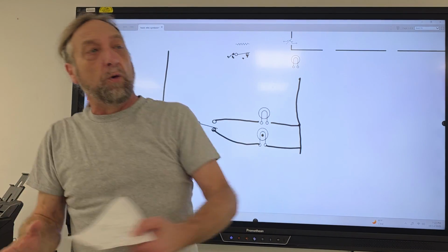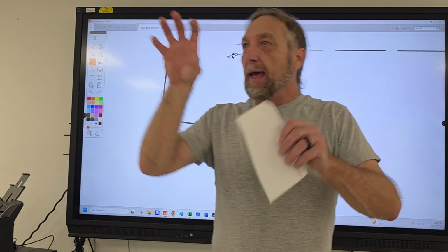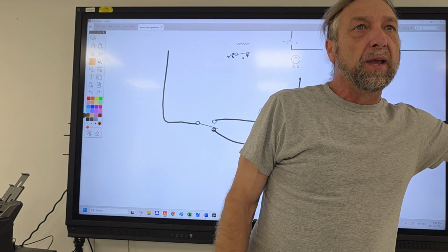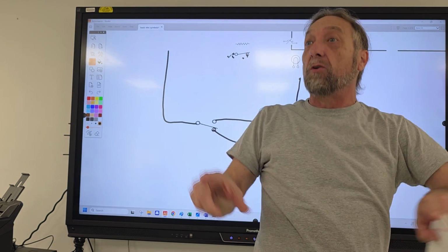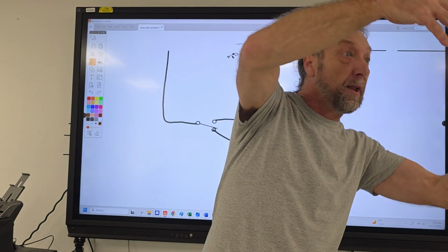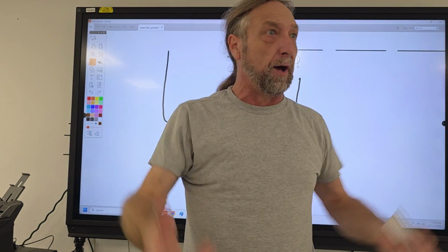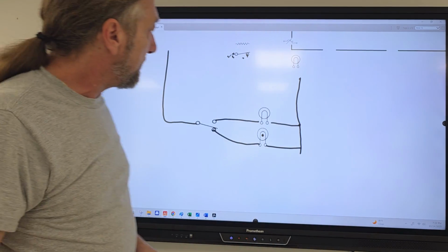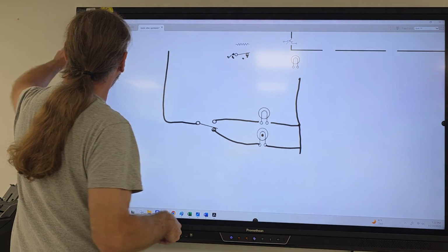You need to take the diagram to the machine, see a part in the machine, find that same part in the diagram, and see how that part is in the circuit and what parts turn it on and off, and how. This is troubleshooting. So let's try a different diagram.